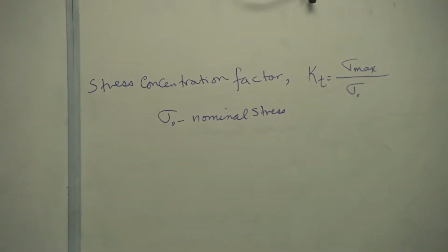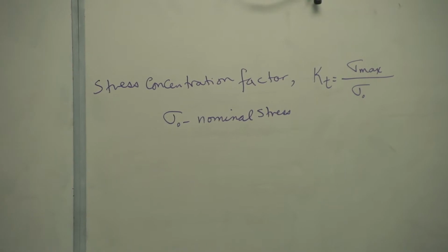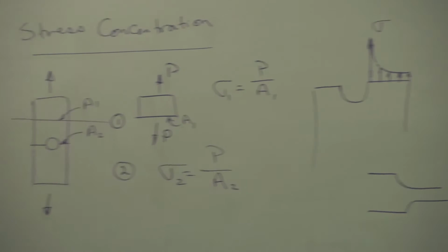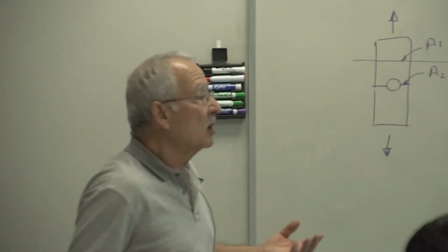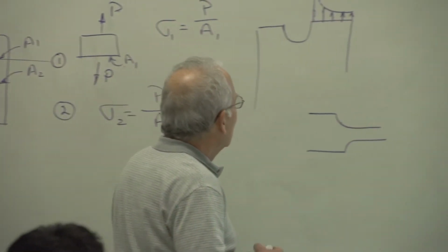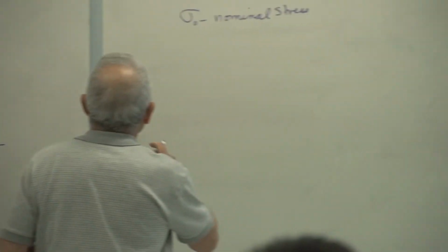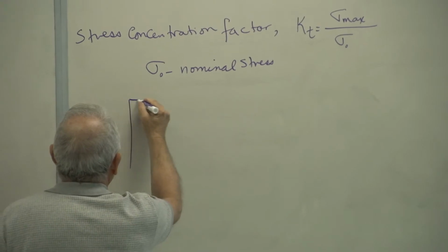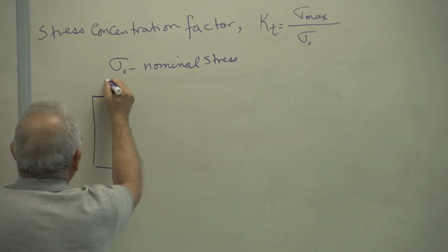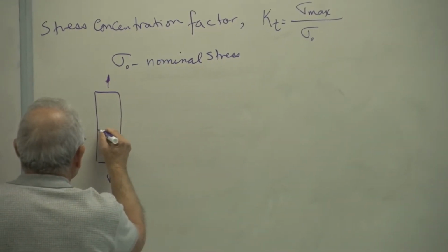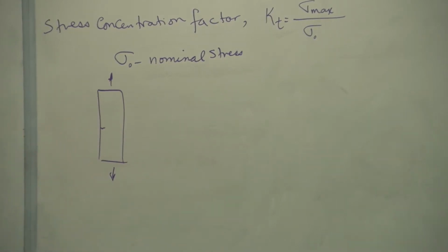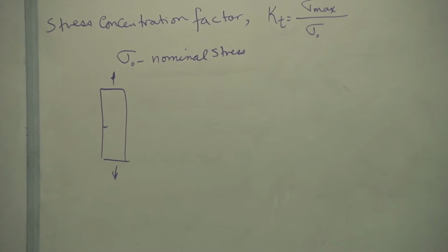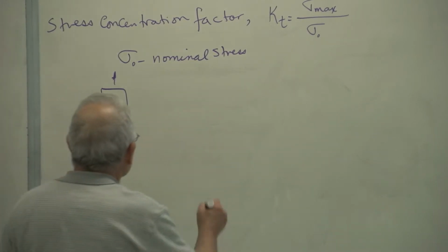This stress concentration factor depends on the size and shape of the discontinuity, sometimes called a flaw. For example, a different discontinuity that I can draw, bigger and you can identify with, is something like this. Let's say a crack. If we look at this crack under the microscope, this is what we see.